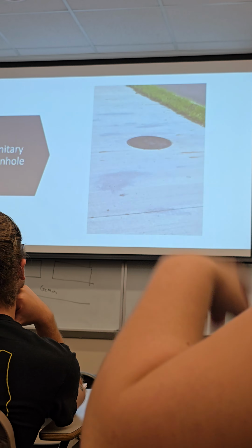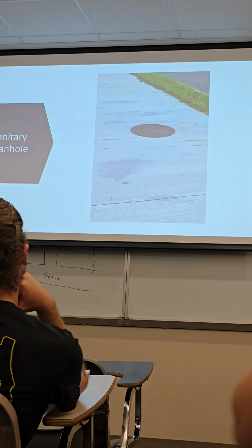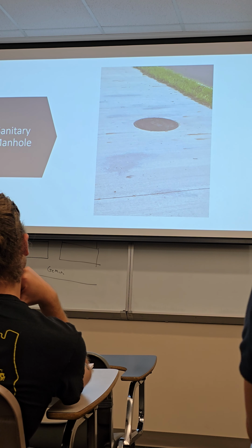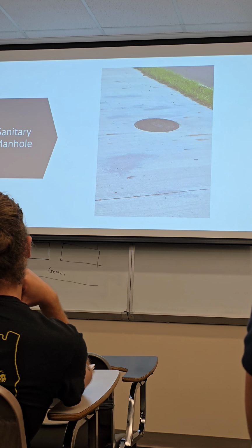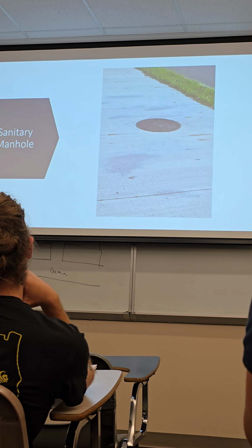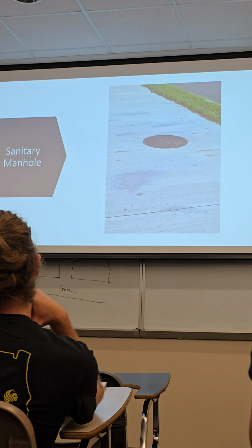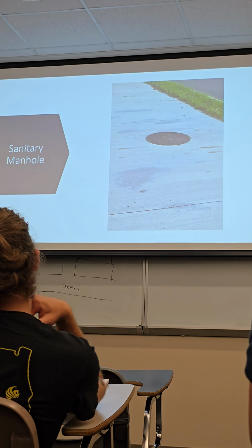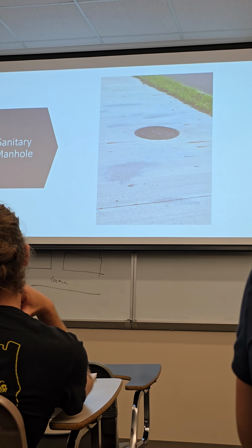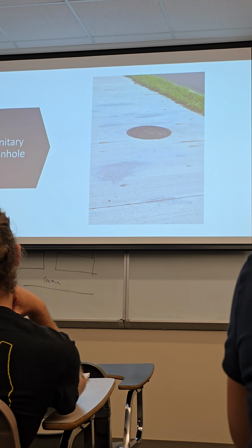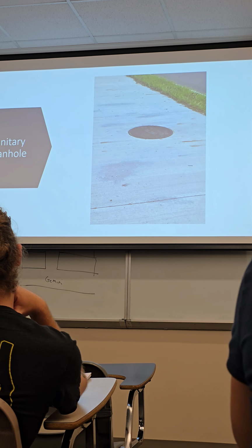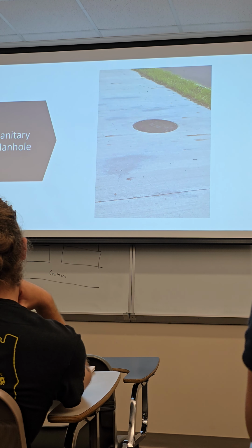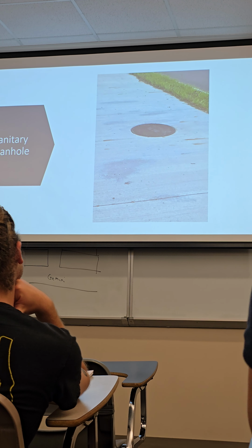Sorry, talking about University, why are the manholes in the middle of the road, basically? There are 3 lanes, and they're in the middle lane, all the way to the left. Why is it in the middle, not all the way to the right or the left, because of the crown? There's a number of reasons for that. First of all, if you ever have to put a manhole in the road, you want to try to put it in the middle of the lane, so you want your car to straddle it. You don't want it to be in the wheel path, as you were saying, which is really not a good thing.